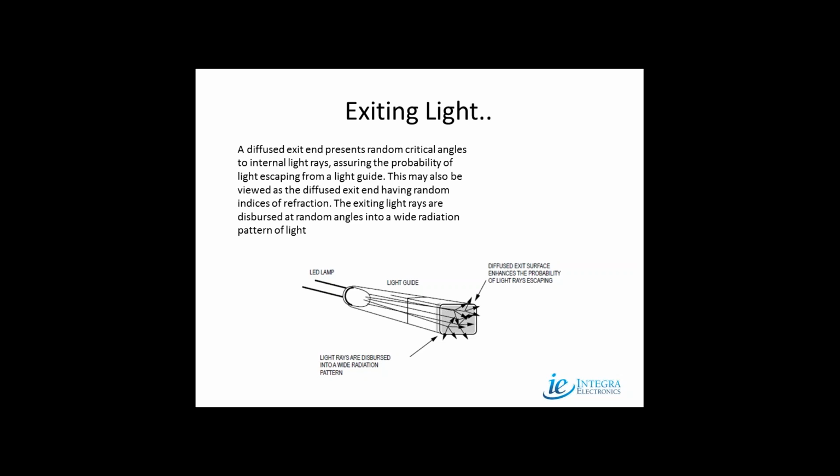Of course, the other purpose is actually to use the light coming out of the light pipe to illuminate some other object that's nearby. And then in that case, you're probably not going to want a diffused light pipe exit as much as you're going to want some kind of a lensed exit that will focus the light onto the areas of interest. That's all.